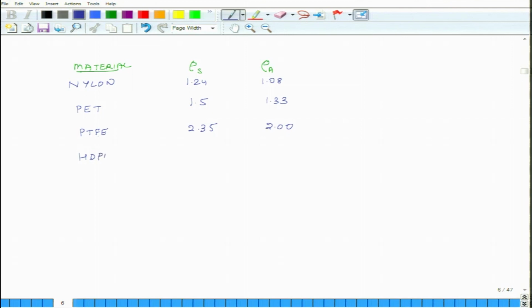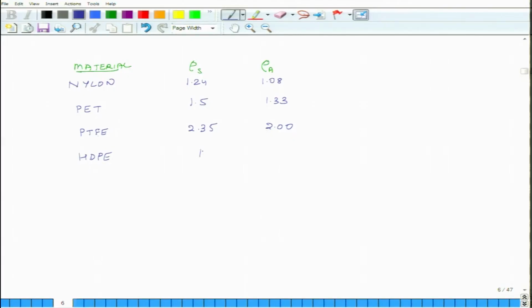HDPE, in a lot of plastic parts, bottles, things like that, if you see on the back side, you will see some letters written on these plastic parts, either you will find HDPE or LDPE. What is HDPE? HDPE is high density polyethylene. The density could be as high as 1 and this could be 0.85. And similarly, you have low density polyethylene. Okay. So, you see that the semi-crystalline version is tighter, it is more compact, so its density is higher. Amorphous version has in general lesser density.